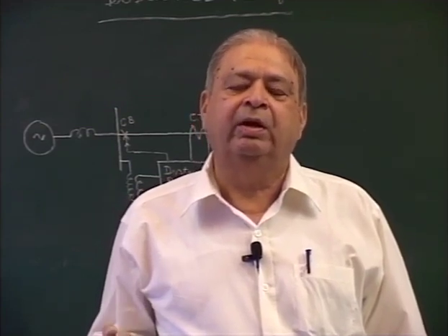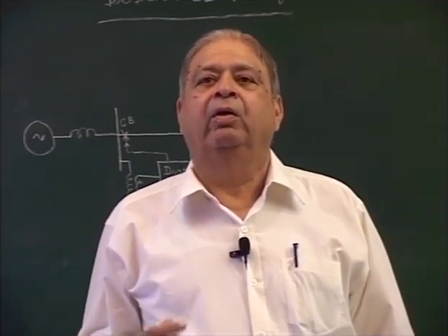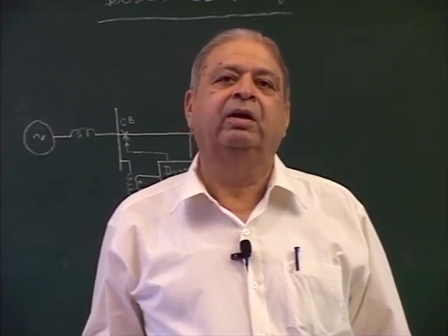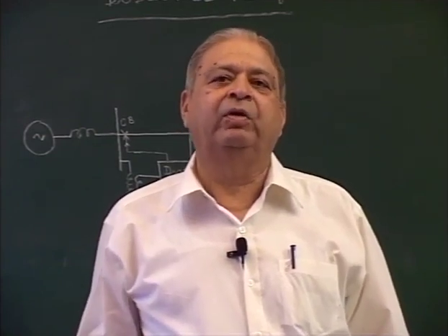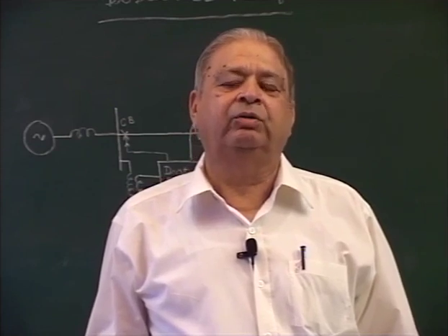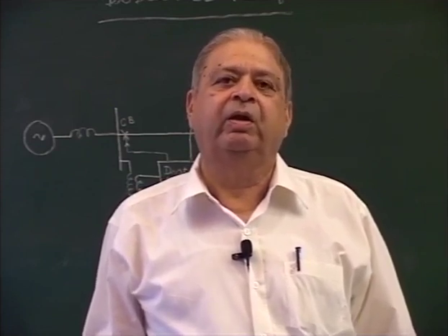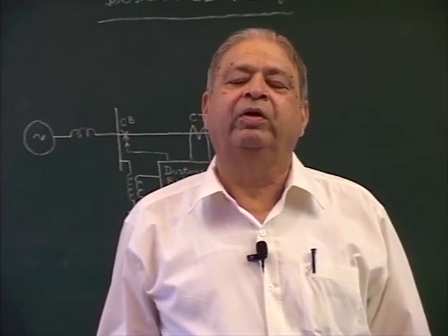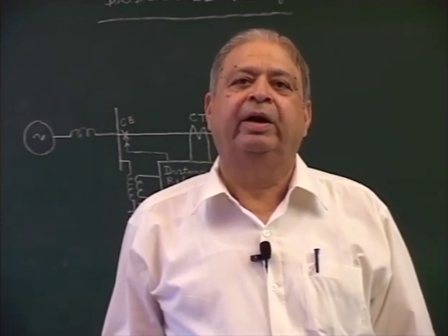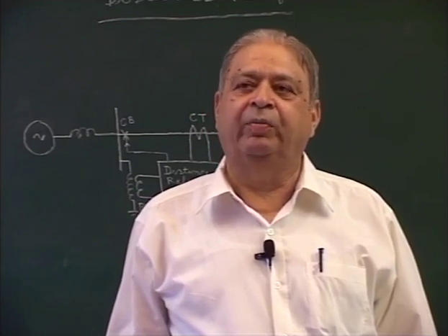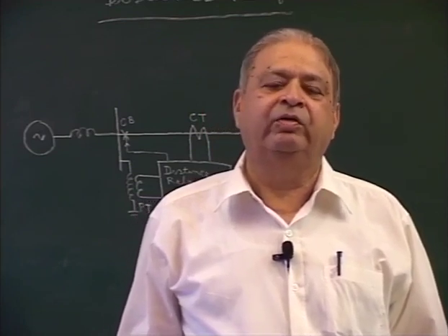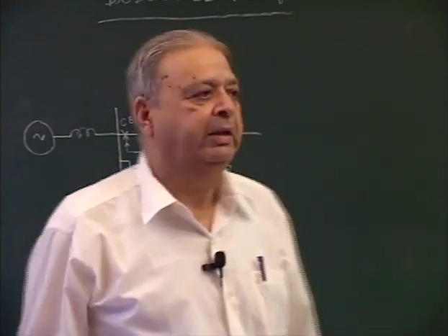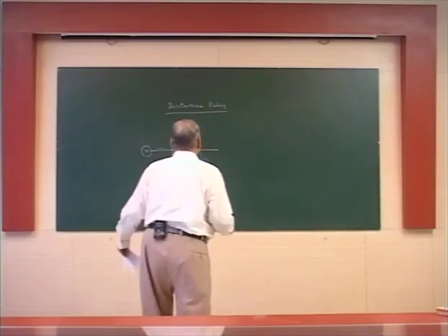Now, these currents, voltages and the value of replica impedance are suitably processed to know the exact location of the fault point and whether the relay operates or not, the decision is taken accordingly. Say there is a fault here.